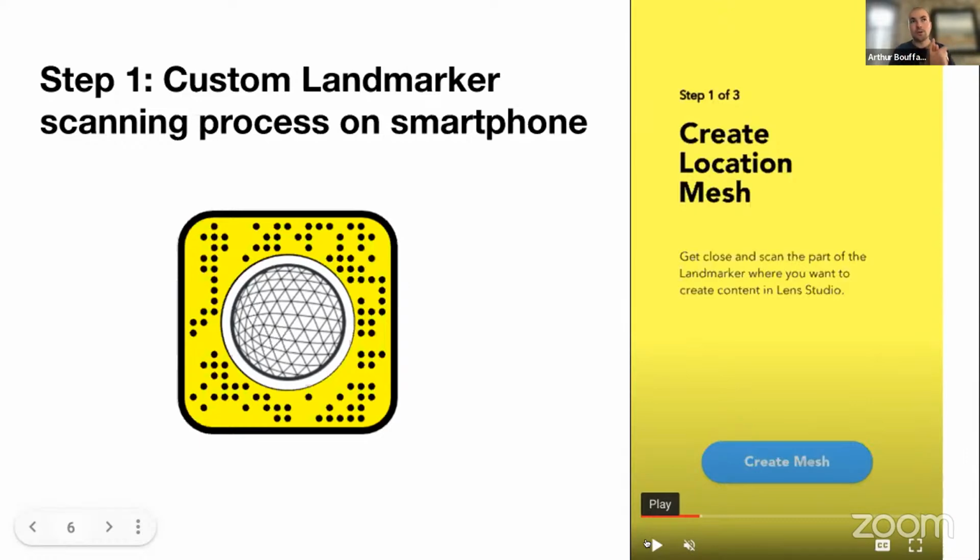So if you want to scan, for instance, a building, you should open the lens facing straight towards the building and pretty close to where you're going to be doing the scan. If you open it in, say, another room, and then you go outside and scan a wall, it's going to keep that initial position in the room and set it as 0, 0, 0 in Lens Studio, which makes things a bit awkward.